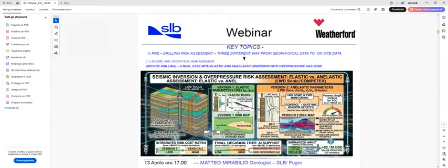Also, we can differentiate the pore pressure, the lithostatic pressure, and the water pressure. So for example, in this case you have, in the blue zone, the overpressure water influx. This is a zone where you are cutting, like making a photograph of this part. You see from the geomechanical and hydrogeological point of view that you have an inflow of water in this part. So it's really important to know this.